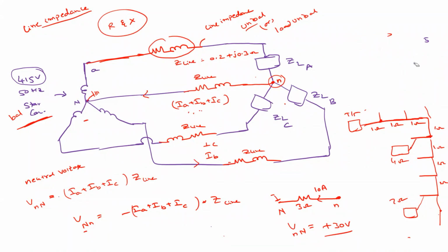But there are certain instances, especially when you have computer load centers or software offices. There is some problem with software office loads, especially computer loads. In that case, the neutral current will be high when compared to the phase currents. Why it will be high is not the point here. In that case, what will happen?